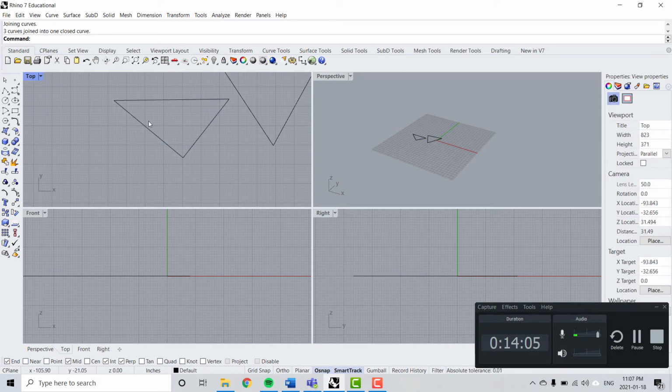And the closed or open curve concept is really important when it comes to 3D modeling. It'll be the difference between having a solid object and a planar open 3D model. So for example, if you had a cylinder, it'd be the difference of having a solid cylinder fully enclosed or having an open cylinder without the top and bottom faces.